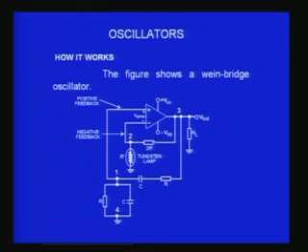Now in the negative side I have used some 2R and R, 2R prime and R prime. What happens to this configuration, I do not know whether you are able to recognize the configuration. I am giving the signal to the non-inverting input, and the inverting input is grounded through a resistor R prime, and 2R is the feedback resistance.